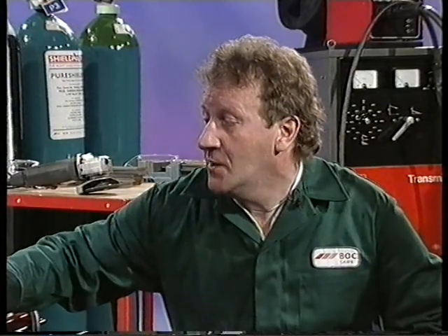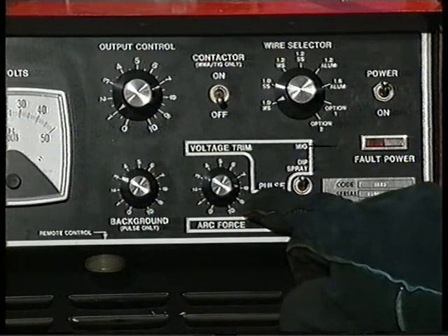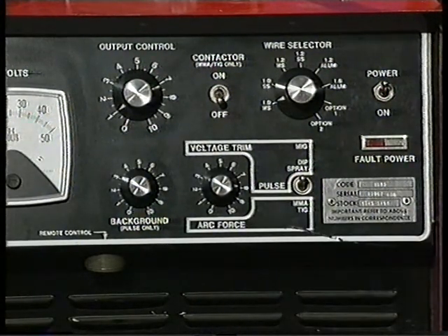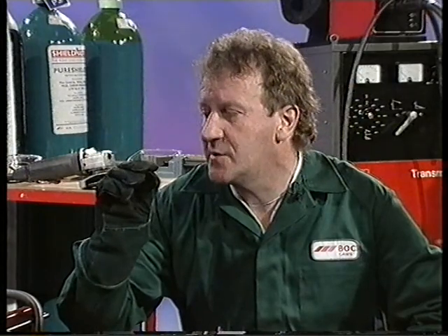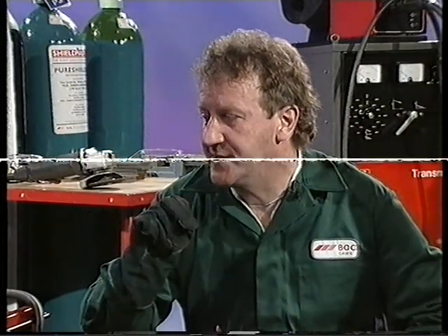The synergic knob is there, that's taking the amperage and voltage up and down, all on the one control. We've got a voltage trim here, and you can see I've selected quite a high voltage trim. This will not give that same sharp dip condition that we heard before. It's going to be quite a lot looser condition, but the more voltage means that I really do have no lack of fusion worries on this minor weave that we're putting into the root run itself.